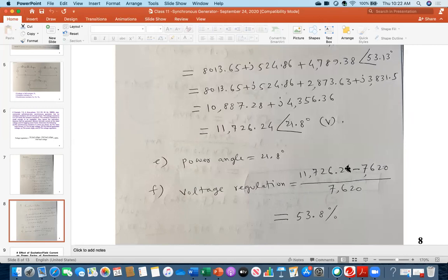That's why you see there is huge difference in voltage, kind of the 4,100 difference. That is too much. That's why you are getting the very poor value. So it is the expectation that when there is no load, the difference is very low so that you get the small number here. As I told you, expectation is like 10% or 15%. Then the system is pretty good.